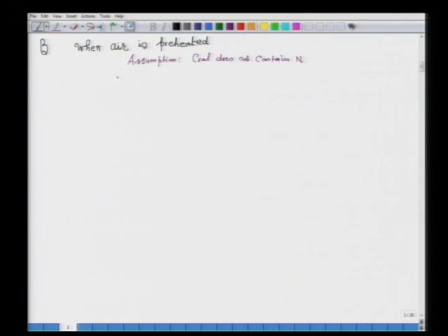So, the nitrogen from air is equal to what we have already calculated, 0.3694 kg mole, and oxygen from air is 21% of this, that is equal to 0.0982 again kg mole.